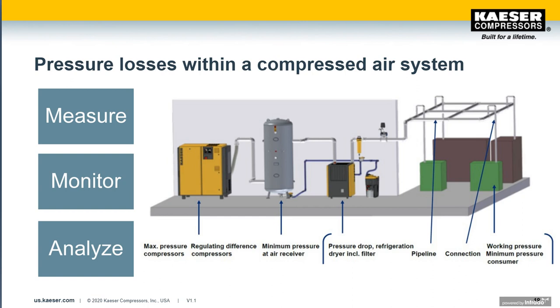So now we're going to be at 107 right there where supply meets demand. If the piping is designed well, we would see maybe a 1.5 psi drop in the distribution network. And if we had 1.5 psi drop in the connections, that's only 3 pounds. So we'd be seeing about 104 psi at those consumers.